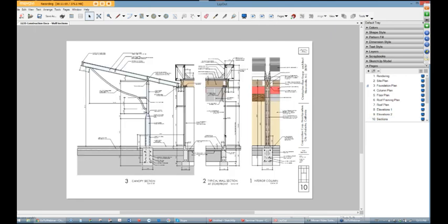As I said before, you can do enlarged details. So these are just little pieces of the section that we already cut, or you can create a section. But these are windowed in. In other words, the viewport has been reduced. These have been set to a scale of 3/4 inch equals a foot. Everything else, for the most part, you've been looking at is a 1/4 inch scale. With SketchUp, obviously, that's even more difficult. Setting up different scales on the same page would be nearly impossible in SketchUp. In layout, these could actually all have been at different scales.